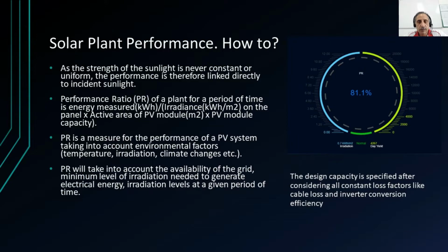There is a method to calculate the performance of the solar PV system, called the performance ratio, which in turn is a factor of the total irradiation of the day and the generation during the same period, together with the installed capacity. This performance ratio is a value from 0 to 100%, and optimal performance would be from 75 to 90%.